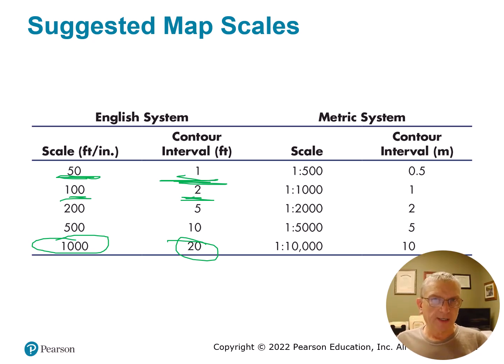But what I suggest for surveyors and engineers is to consider how much room you need around the subject area that you're drawing, the property, the contour map, the plans, the detention pond, the bio recharge area, whatever it is, and how that fits the sheet size. Because even if everything's done and submitted and shared electronically, at some point they need to be, if they're done right, so that you can plot them to a scale and it looks like it should if it was all paper the whole time. Some agencies and municipalities still require paper submittals.